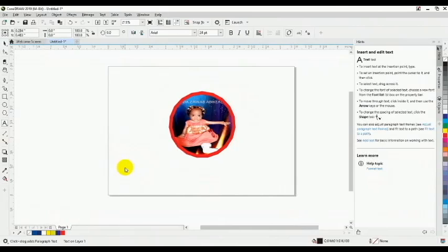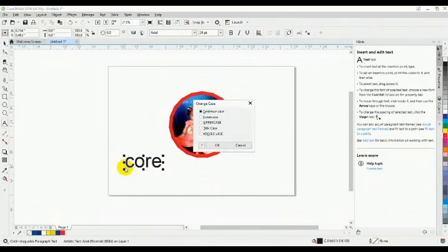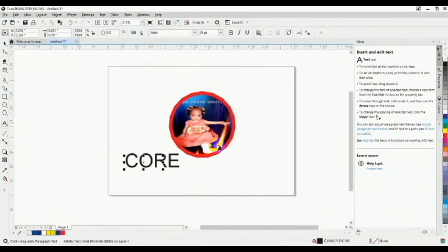Aside from this, now let me move back to the text tool. And in this text tool, the text tool will tell you what to write. For instance, Corel. So all this is the text tool. You can play away with it. You can change it to capital letters by pressing your Shift key and F3. So you can see all this. If you want lower case, just use this and press OK. Automatically it will change to Corel, and then you can use it.